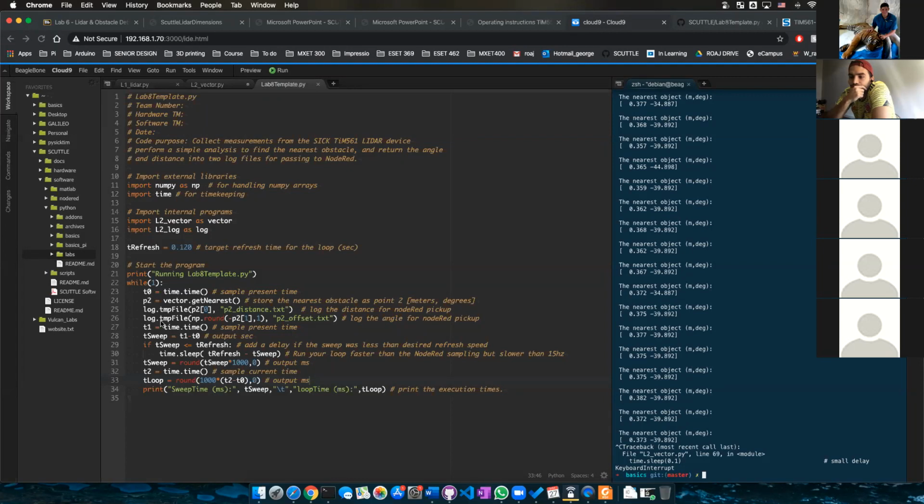If you took a red laser pointer, that point is only going to hit what is directly in front of it. The laser beam technically does spread, but for the most part it doesn't get larger and larger. I think of the ultrasonic sensor more as a flashlight: whatever the light hits first is either going to be your measurement or it's going to be influencing your measurement.